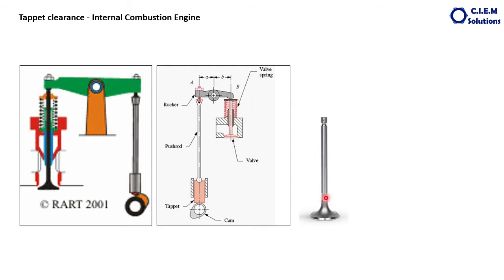This is the valve. In any internal combustion engine, valves, cylinder head bottom surface, and piston are the parts directly exposed to the combustion chamber, where 1500 degrees centigrade of heat is generated during the combustion process. So cylinder head surface, valve seats, that is the valve, and the piston are the parts exposed to the maximum heat inside the engine.